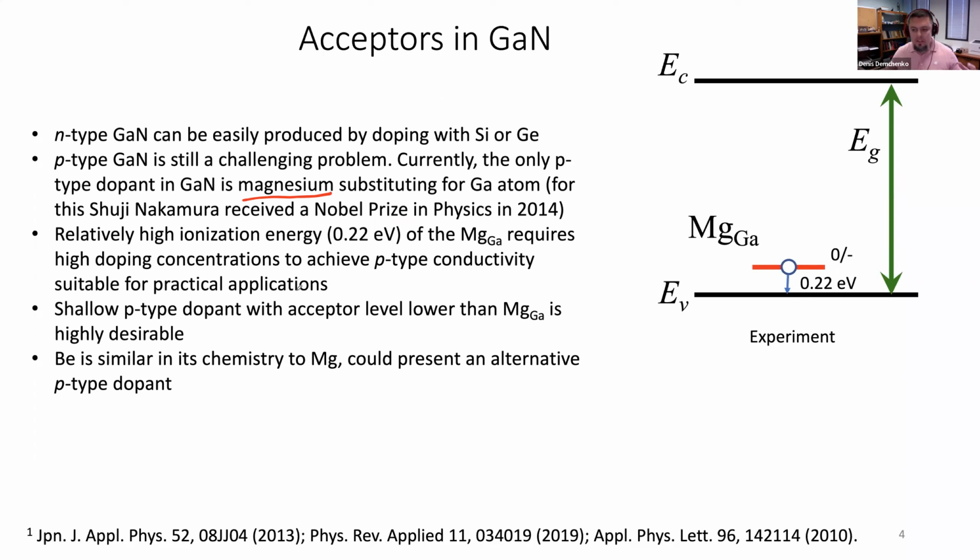The problem you're trying to solve is that if magnesium goes into gallium site, so for example, this defect here, the way it's labeled, magnesium with gallium subscript, that means magnesium on gallium site, it's an acceptor. But if magnesium goes into interstitial site instead, where it also has relatively low formation energy, it's a shallow double donor. So magnesium acceptor kind of kills itself during growth, and usually samples come out to be high resistivity. But if you co-dope with hydrogen, hydrogen-magnesium complex is electrically neutral. And so it comfortably goes into gallium site, sits there, sample comes out high resistivity, and then you anneal it, get the hydrogen out, and activate P-type conductivity by basically isolating magnesium acceptor. And that's what made the breakthrough for P-type gallium nitride.